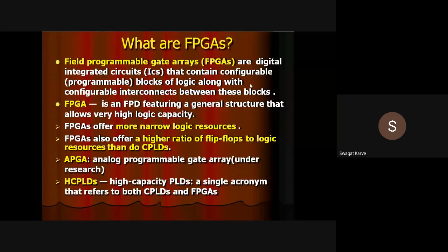Okay, while discussing the tree diagram of the integrated circuit: full custom, semi custom, and PLDs. So PLDs are again in two categories, CPLD and FPGA. So this FPGA is nothing but a subcategory of PLDs. So in very simple language you can say FPGA is a high capacity PLD, right? You can say it is a high capacity PLD. Even you can say the same thing about CPLD also. So there is not much difference between the CPLD and FPGA.